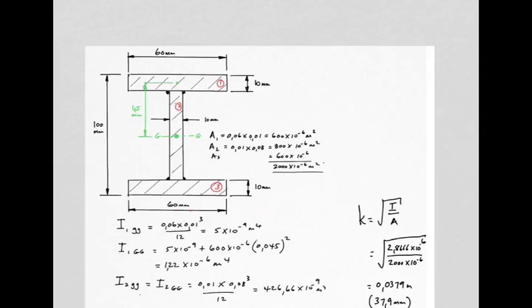Next step is to take that answer of second moment of area about the shape's own centroid and now convert it to the distant axis where you actually want the answer. So you want the second moment of area about this axis, which is some 45mm away from where you have it currently. For that, you're going to use the parallel axis theorem.